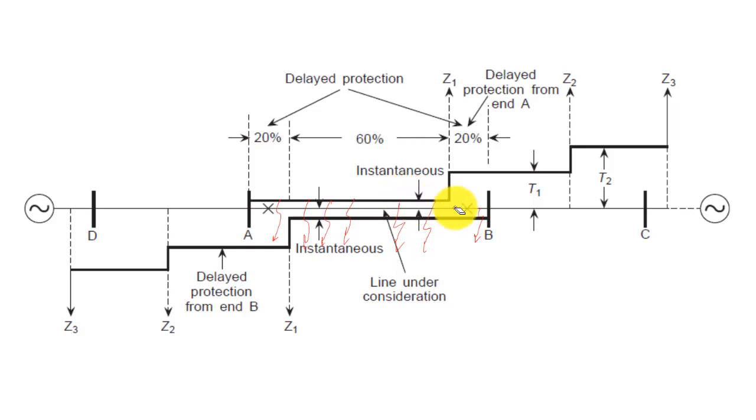So how to make this possible? Suppose the fault happens at this point, at the local end towards A. If we can transmit the signal, that is the voltage and current seen by the relay, VR and IR both, very quickly to relay B, and relay B can process this information, then relay B will also operate instantaneously, very close to the relay A operation.